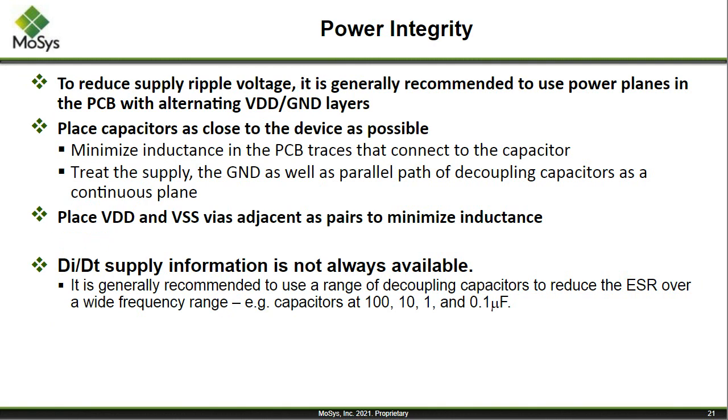The next thing, one of the last things we'll talk about in general, is power integrity. Obviously, power is very important in PCB routing. And the one thing you want to make sure is you get as much plane, an uninterrupted plane as possible. The power planes in PCBs, again, we're all using multiple VDDs on devices now. You'll have 3, 4, 5 different VDDs going to a device.